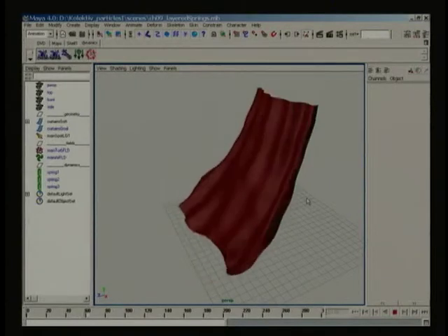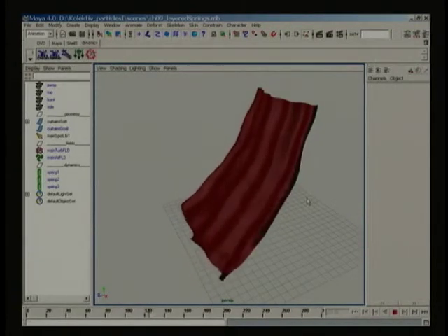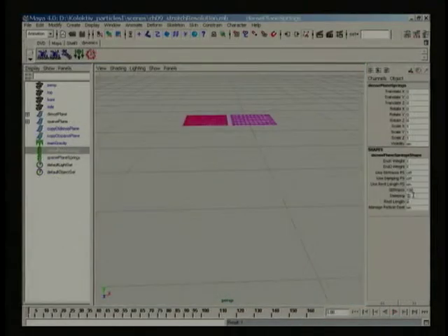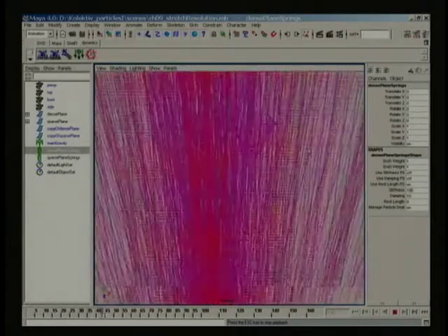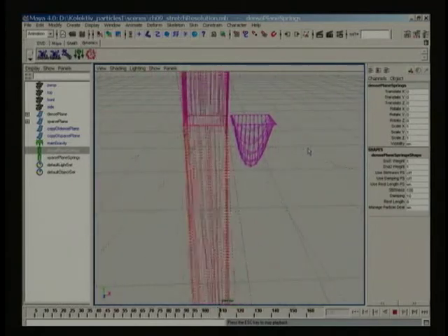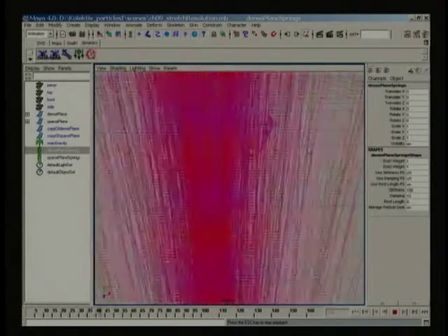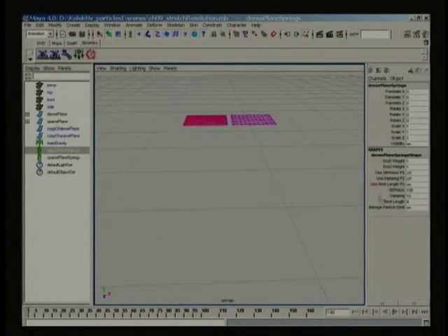Basic techniques involving springs and a low goal weight work some of the time, but you're usually left with a simulation that's difficult, if not impossible, to control. Adding too much control by increasing your spring strength can sometimes result in spring tolerance errors, where your simulation breaks down into a garbled mess of particles, geometry, and springs.